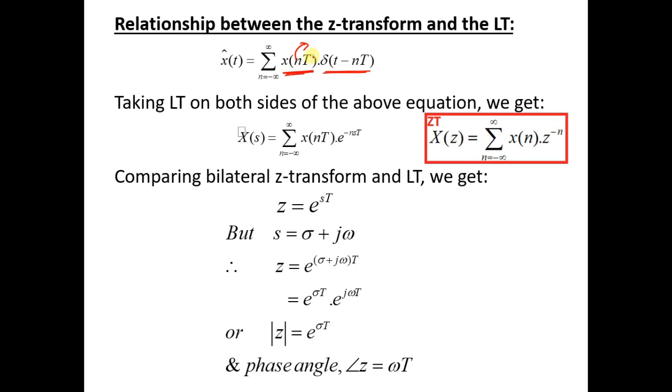So we have a frequency related to xn, and when we sample the signal, if you remember, we discussed that we band limit the signal. When we try to go for the sampling of the signal, we band limit the signal. That means we restrict the signal frequency components. So if we consider the maximum frequency of a signal to be FM, the lowest would be 0. So the frequency component would be 0 to FM.